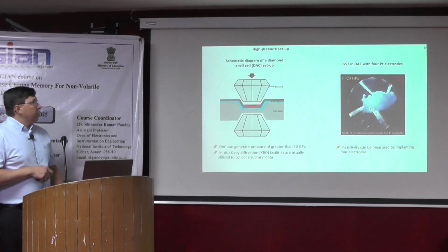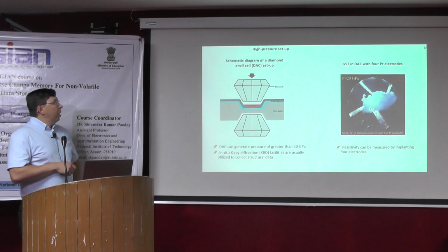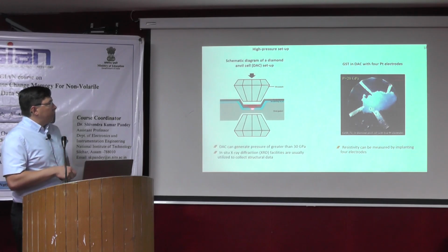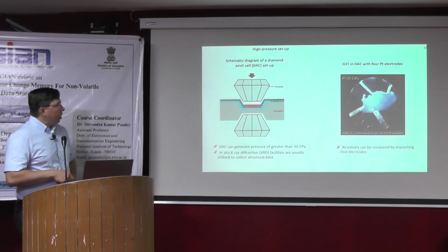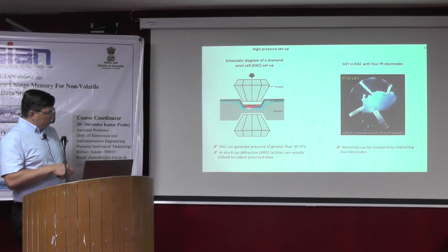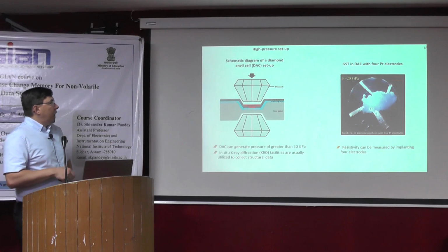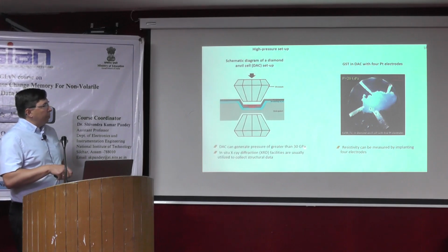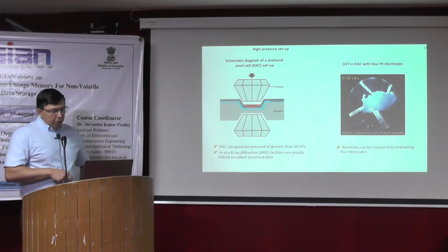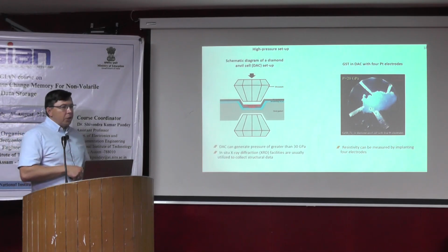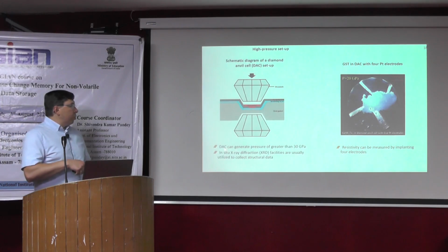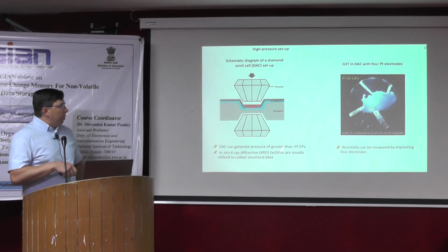phase transformation? For this we need a special setup, and it's based on the diamond anvil cell setup. Here this is the image. It shows two diamonds, and here this is the GST powder. By moving and pressing these two diamonds, we can reach pressures of more than 30 gigapascal. And because the amount of our powder is not so large, we study this transformation using in situ X-ray diffraction, mainly by synchrotron.